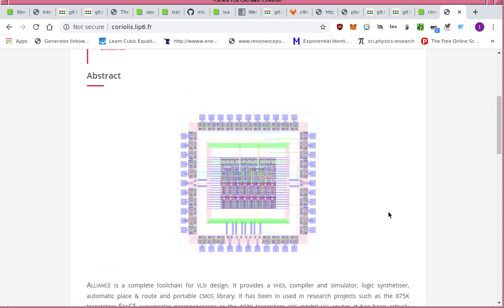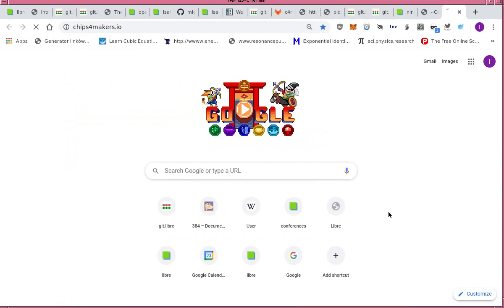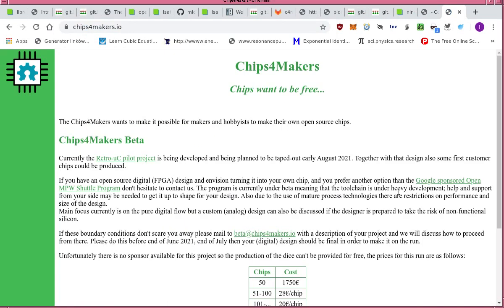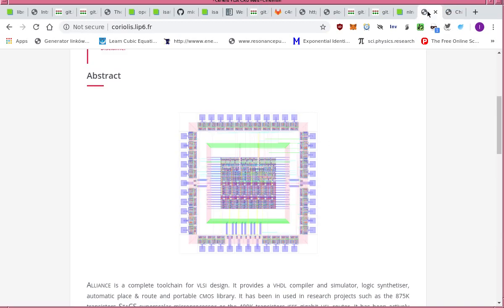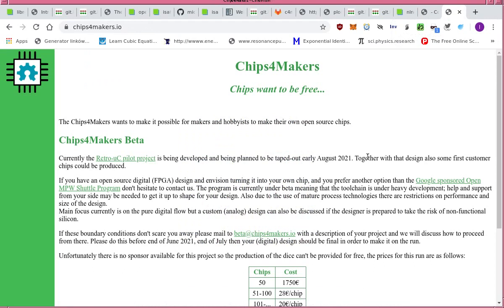The other thing is that chip flow makers have created a cell library, which is needed here. We'll go over this a bit later on. They have created a cell library, specifying it in Python, where you run the Python program to generate the cell libraries given what is called the PDK, the Physical Design Kit, for the foundry. Now, in most cases that's under NDA. However, fortunately, there's a couple out there.